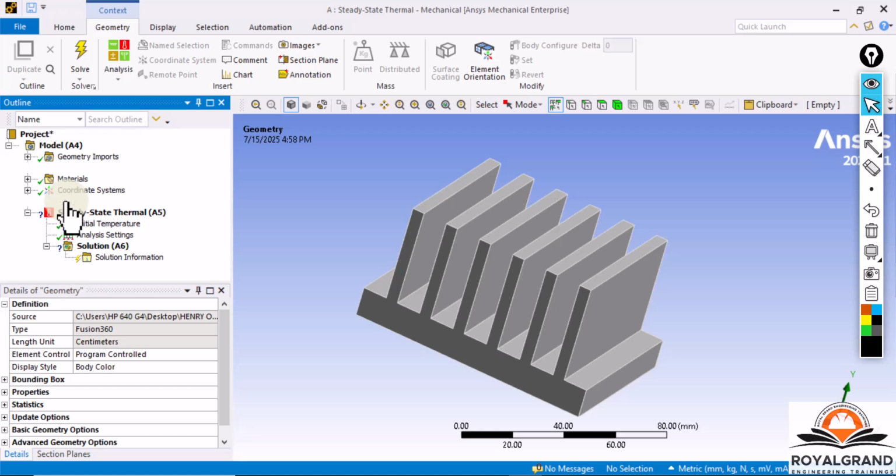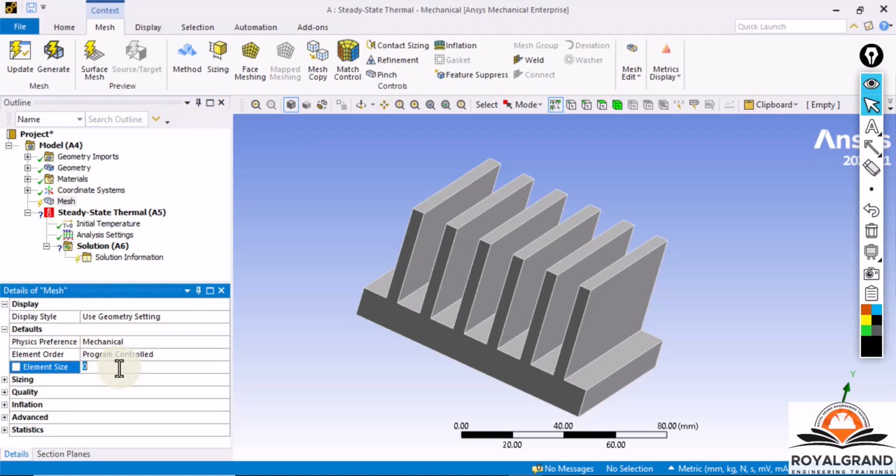So I will click on the mesh and change the element size. I will say 20 millimeter. Let's start with that 20 millimeter and try to view it. This 20 millimeter is displayed here by this circle that hovers around the cursor. You can see it's trying to tell you the size of 20 millimeter relative to your canvas. You can see it's very, very big, which is too big, so I'll change it to 5 millimeter. I'll enter 5 and press enter. This is a little bit better, but it's still a bit big. So let's say we can work with this actually.